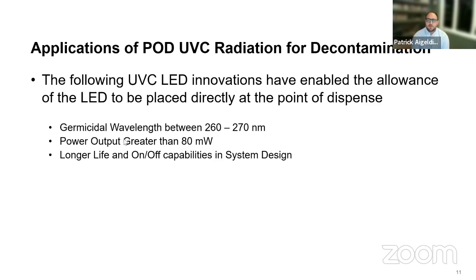And the longer life and on-time capabilities really allow these system designs to implement it right at point of dispense and not have to have a maintenance cycle. Previous technologies would have to be changed out on a yearly basis. LED life has extended over 10,000 hours to the point where in effective system design, the LED will last the life of the system.